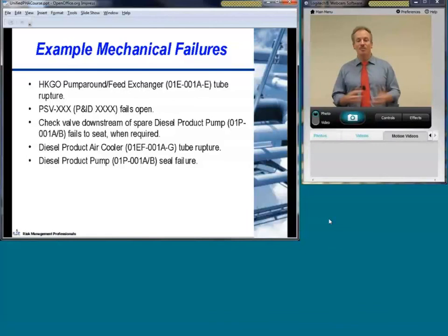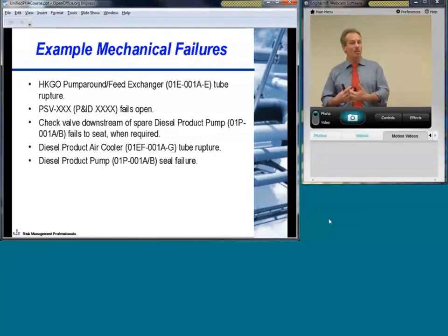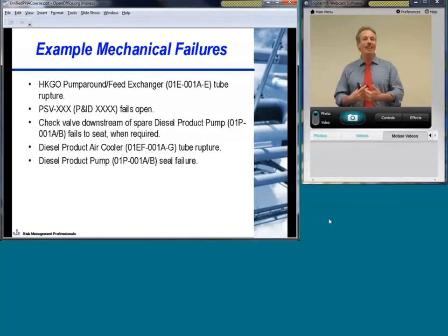Bottom one, pump seal failures. A lot of pumps are now being installed with the extra money put up front to prevent problems later: dual tandem seals, monitoring devices, and better quality seals that decrease the likelihood of this, but you still have to be very careful. A seal failure, often if you're looking at a refinery or other types of process facility, can result in a fire condition, but during the HAZOP study you also want to look at what else is laden in that flow stream. Could it be H2S or some other toxic material?